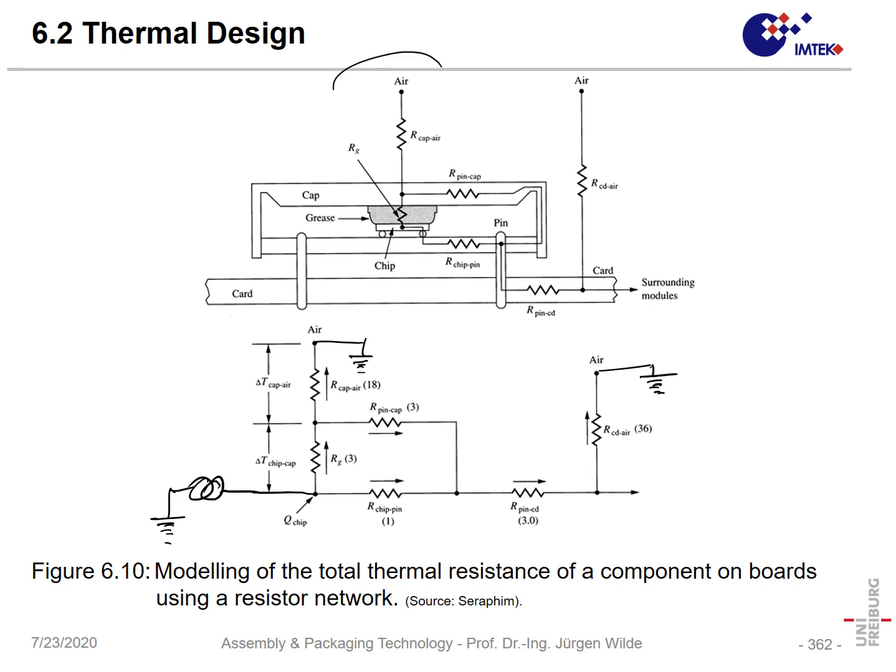Where you often make a really systematic mistake, where you can be wrong by orders of magnitude, is really the heat transfer to the environment by, for instance, air cooling. As I mentioned, that heat transfer coefficient can be between 1 and 10 watt per square meter Kelvin, and so that value can really have a big effect, and that means it is always important also to make fluidal computations in order to get precise values.